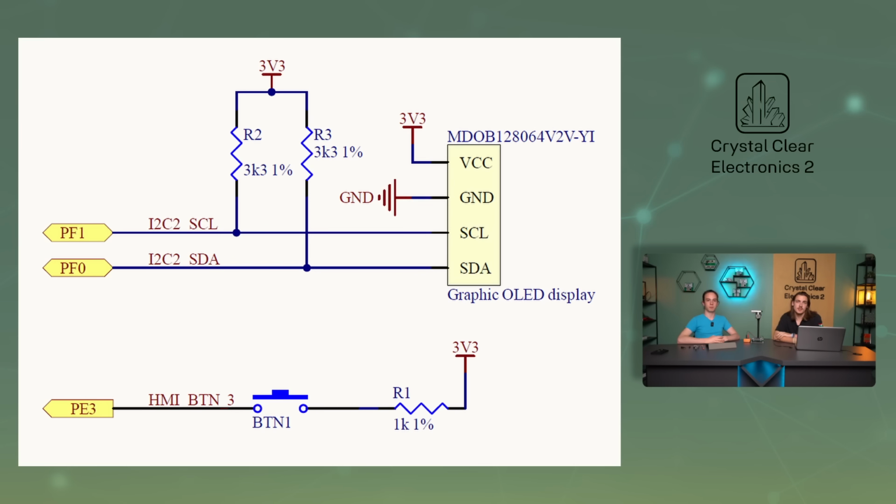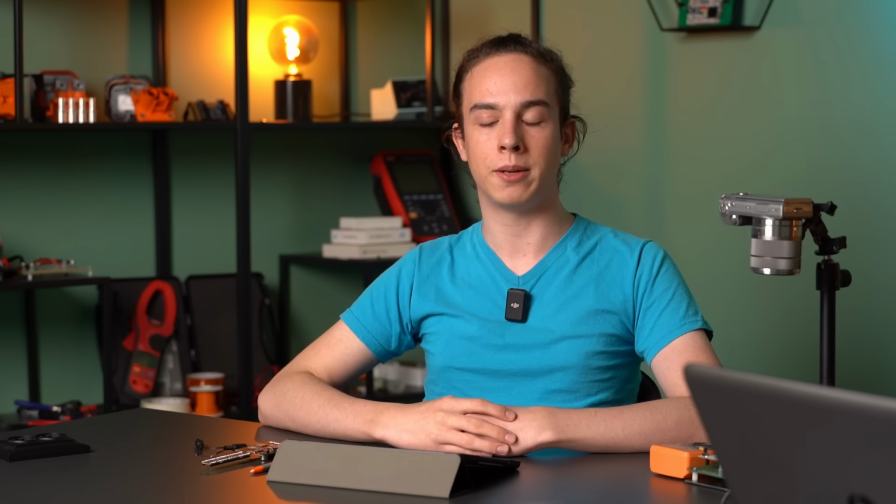Our assembly on the breadboard only contains a push button and a display at the moment. The example program works and is used like this. After reset, the program starts in run mode. Press the push button to move between the menu items, the names of which are shown on the OLED display. After selecting a menu item, a short countdown will activate the mode described by the selected menu item. The display is then switched off. To step to the next menu item, you have to press the button, except for the standby mode, because in that case, the microcontroller is woken by the RTC wake-up timer after 5 seconds.